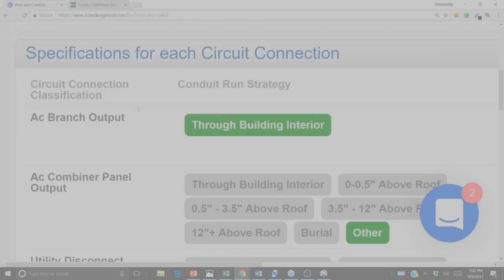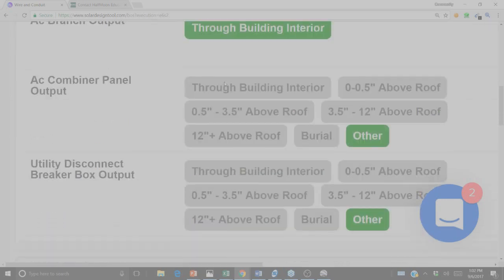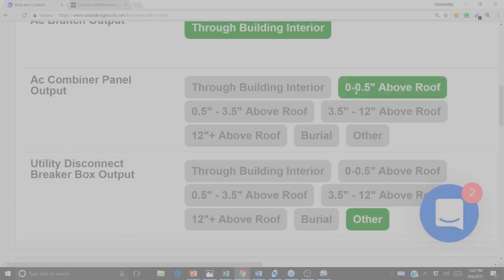So anyway, then we get to our branch circuits and we see there's questions about, well, how close is the conductor to the rooftop? Well, there's different temperature derating requirements that have actually changed in NEC 2017.